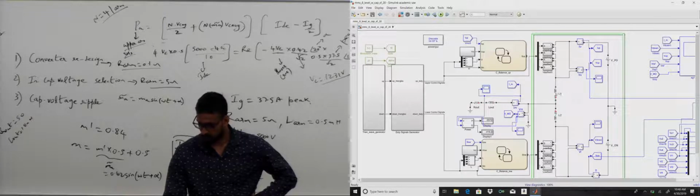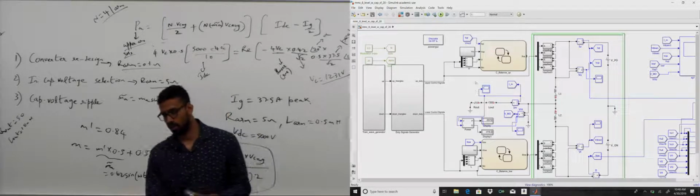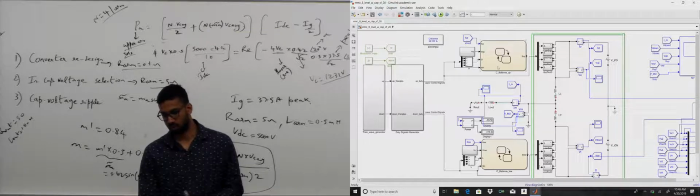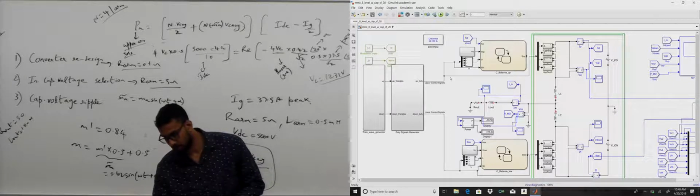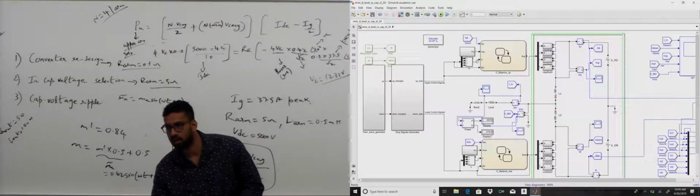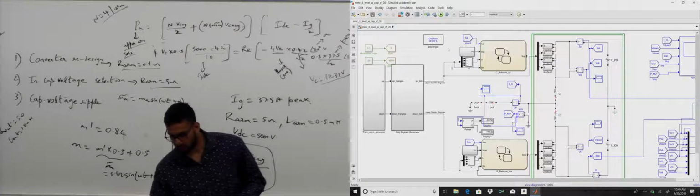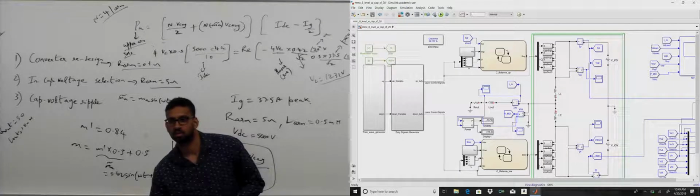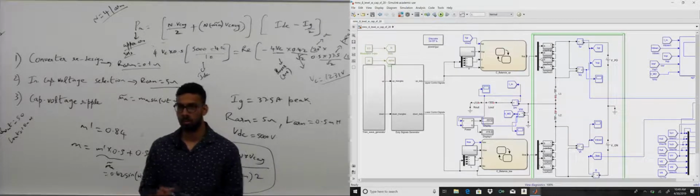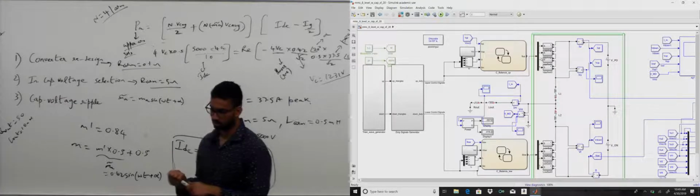what else should we do? Oh yeah, and then an important thing. Do you see this yellow block here? There are 2 yellow blocks, and upper control signals usually go through this control path. It is summed, and the net sum pulse is taken, given to the balancing block and redistributed to the submodules. We talked about this briefly. What you should do is bypass this, connect the upper control signals directly to this mux here. Bypass the voltage balancing and sorting circuitry.